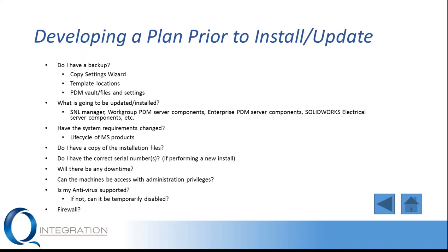So let's take a look at developing a plan for our installer update. The very first thing I think we should ask ourselves is, do I have a backup? Do we have a backup of the user settings? Do we have a backup of the template locations? Do we have a backup of our PDM vault, the files that are in there, any settings that may go with that? This is very, very important that we back this information up prior to installation.